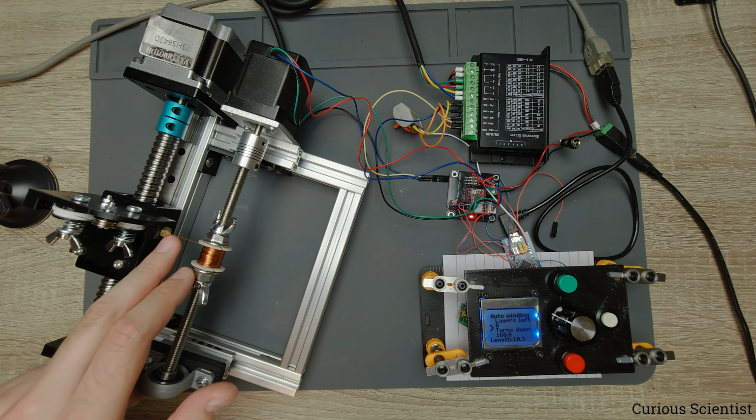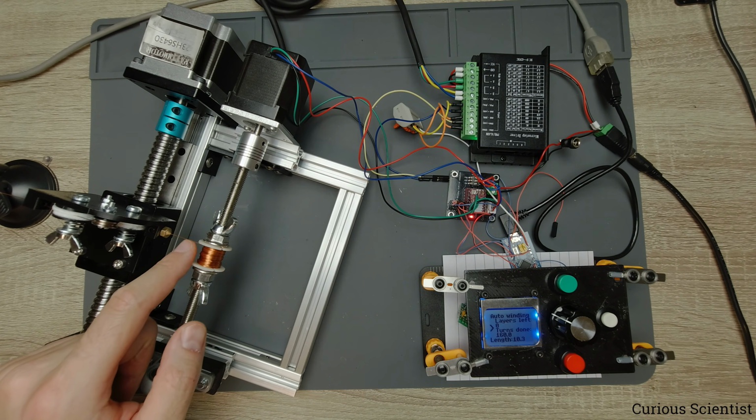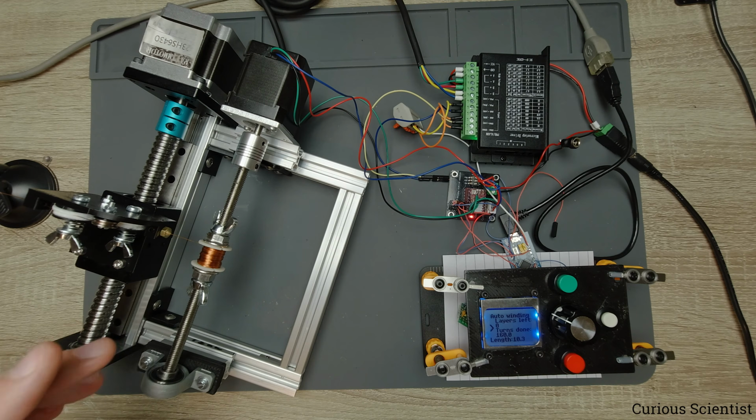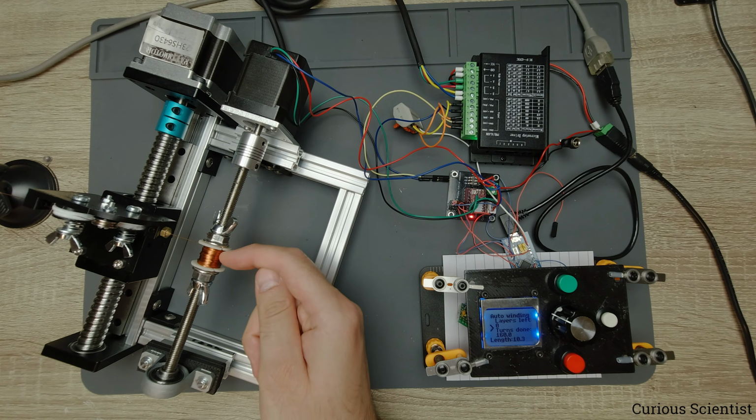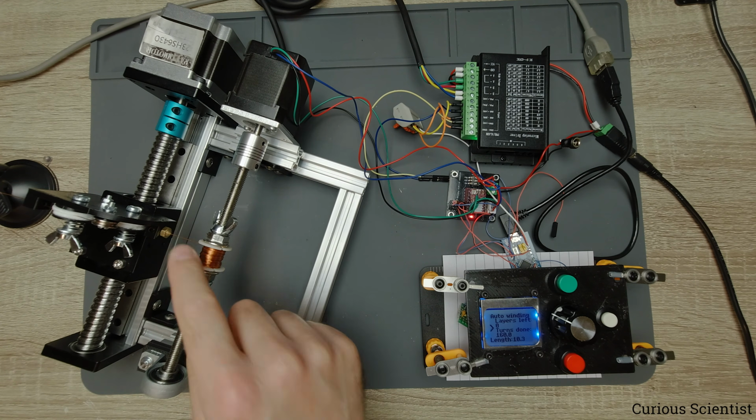I have to find a better nozzle which is a bit closer to the coil, so it forces the wire to go in the same way. And also, as I mentioned previously, the wire diameter could be larger than the nominal diameter, which could be the case here. So because of that, the coil was built much quicker than the feeder was moving, because the feeder's speed is perfect.